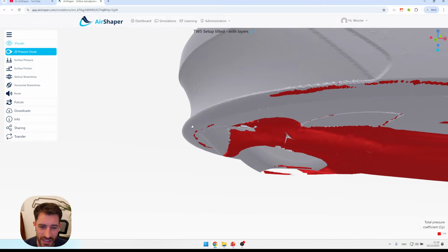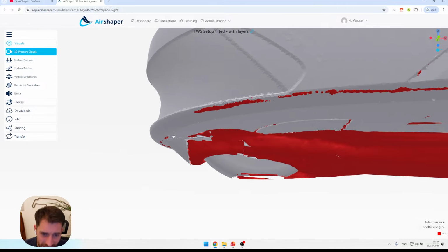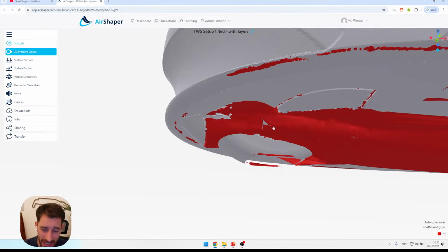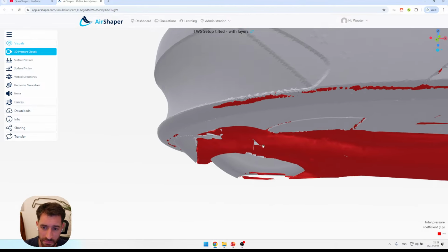And then we have this air deflector, which was an add-on part, connected to the bottom of the front splitter to divert the flow around the front wheel so that the wheel itself would be shielded, because the wheel itself rotates and has a very rough geometry, not in this simulation, but in reality you have your tire tread and so on, causing flow disturbances as well.